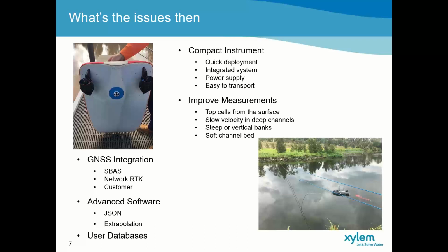If we look at the current GNSS integrations, SBAS is a huge requirement for getting an accurate GGA reference track. SBAS, unfortunately, is not available in Australia at this stage, also not in New Zealand, and some of the Asia Pacific countries. So not having the ability to use that correction process limits the use of GNSS significantly, especially in Australia.